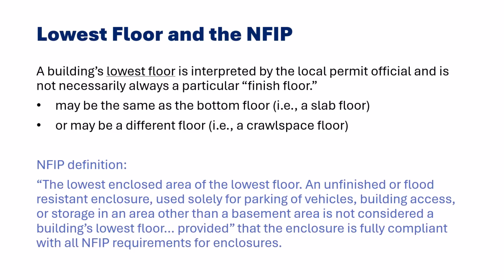So, what is the lowest floor and why does it matter? You'll need to know how to interpret which floor is the lowest floor, because it's not necessarily a direct measurement. The lowest floor may be the same as the bottom floor, or it may be a different floor. The NFIP defines the lowest floor as the lowest enclosed area of the lowest floor.